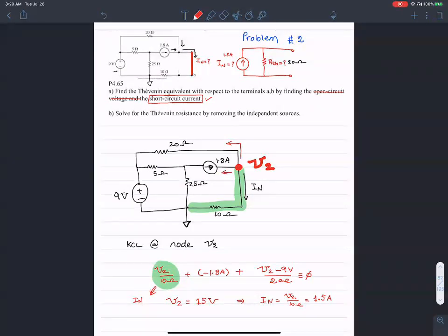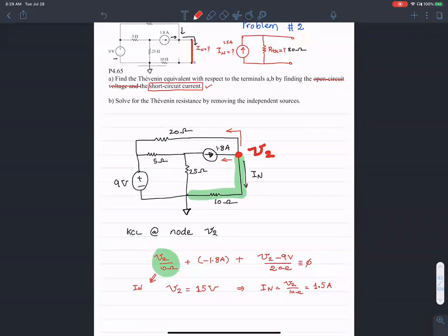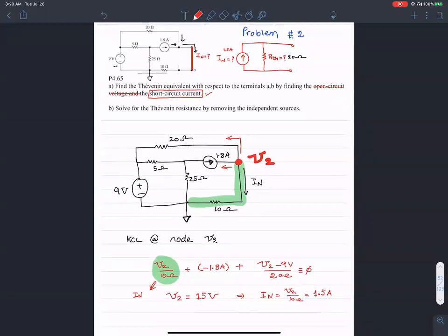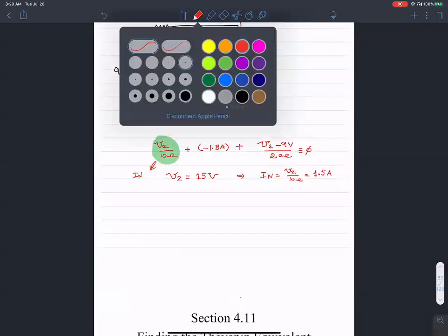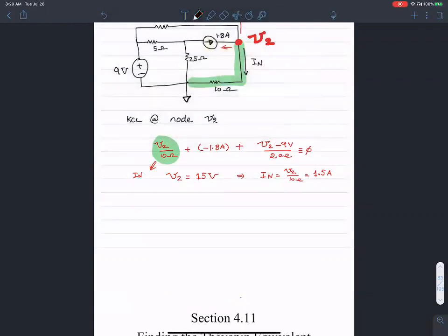Okay, so let's quickly recap. For the same circuit on the top, if I did the Thevenin's equivalent, I came up with something like this, plus minus 30 volts, with a series resistance of 20 ohms. This is the Thevenin's equivalent.